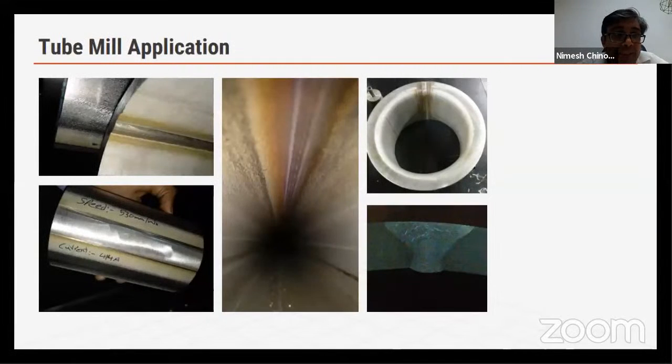The kind of bead you can see, now this was a smaller thickness, maybe 4 or 5 mm, welded at 530 millimeters a minute. This is the kind of bead penetration you can get on the inside, consistency of the bead throughout the pipe length. It passes all the flaring tests and other bend tests that you go through, no cracks over there. And the macro is all good to go.